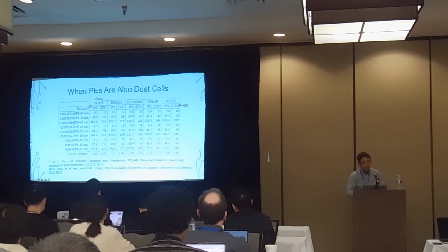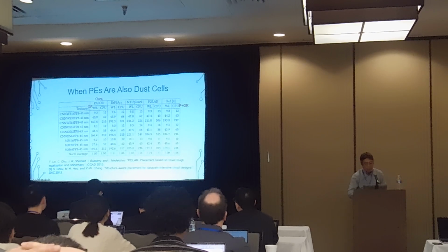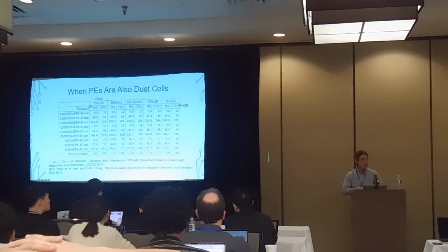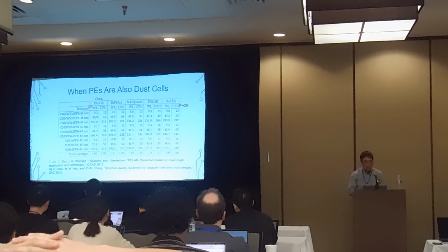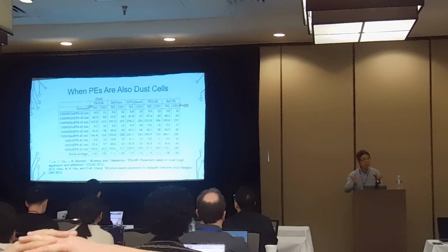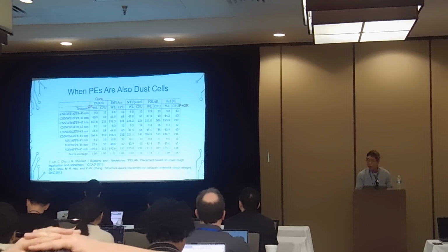So here the variant, this is not the half-perimeter wirelength variant. This is the global routing variant. So it is more accurate, and we can see that compared to RePlAce, and all these methods except the datapath one, we can reduce the global routing wirelength by about 10%. That is quite significant. Again, I'm not saying this is very fair because we're customized. They're mostly general purpose. Again, to show you there's room that we can benefit from. Okay.